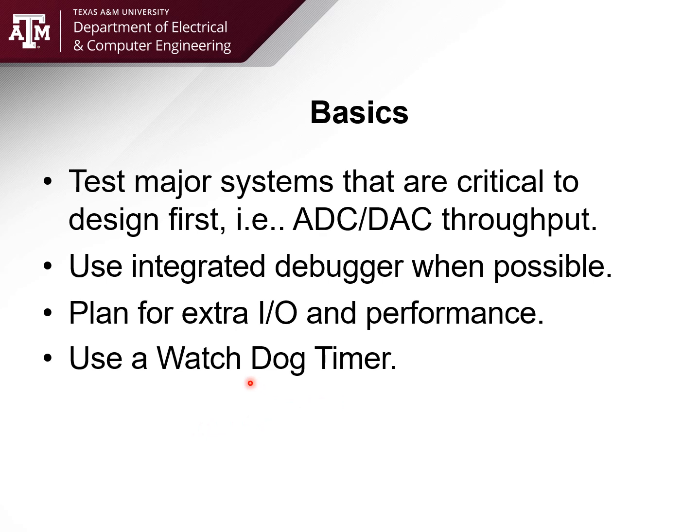When you leave out the WDT, which is an easy thing to do because you don't have to deal with resetting it, it's fine in a debug environment or a design and development environment. But when you go to releasing a product, you want to make sure this is installed and working.